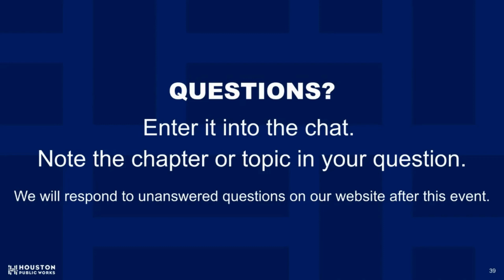Thank you. Next question. Do driveway projects require subsurface utility exploration? No, driveway projects do not require this. Is a subsurface utility exploration quality level A required if the proposed utility is parallel to the existing utility? Yes, a quality level A is required at intervals of every 500 feet within the limit where there is less than sufficient horizontal clearance as indicated by the quality level B, C, or D.